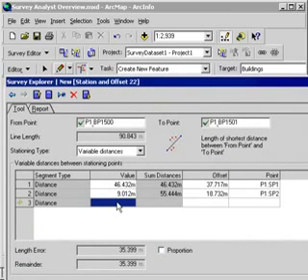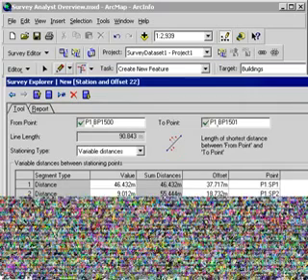So let's continue with this building. The next stationing is 14.9446 meters with an offset of 26.047 meters. And this will identify the third point in that building.